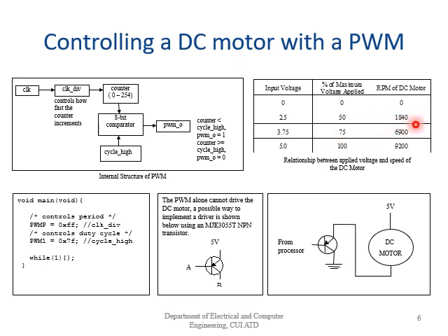So here there is a mistake. It is not 1840 for 50% of the duty cycle. This speed is going to be 4600. So that's why I have told you that for 4600 we need to set a duty cycle of how much? 50%. And we cannot just connect a DC motor to the pulse width modulator because PWM does not provide enough current to run the DC motor. To remedy this problem, we use an NPN transistor to drive the DC motor.